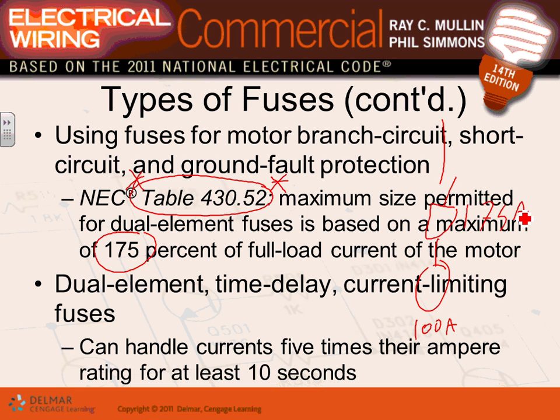And in the overload condition, guys, the dual element can handle up to 5 times for 10 seconds. So it's almost like a heater. It'll provide you a backup overload protection.